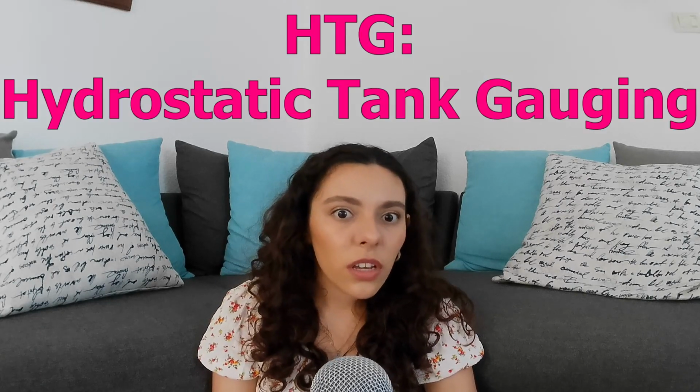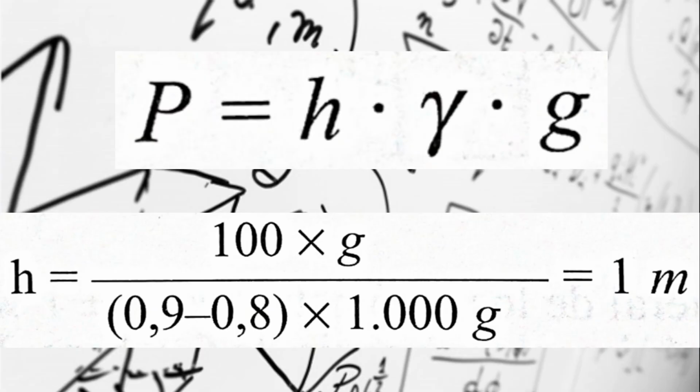In the case of direct measurement of the mass content by means of hydrostatic pressure, HTG, hydrostatic tank gauging, where maximum accuracy is of interest, a PT100 resistance probe is used, which makes it possible to compensate for the difference in density obtained. The differential pressure measured by the instrument is calculated with the first formula, and if the density measurement field should start at 0.8 to 0.9, and the instrument to be used has a margin of 0 to 100 mm column of water, the distance between the intakes is calculated with the second formula.